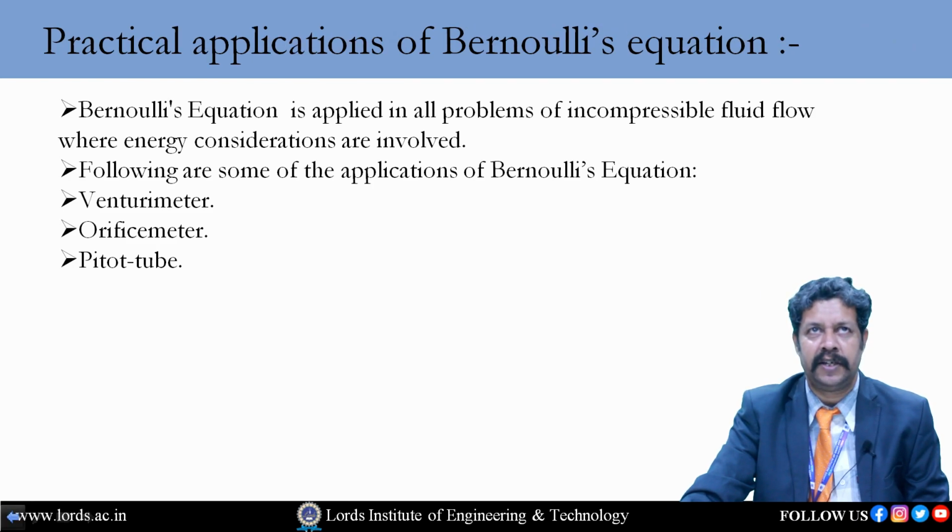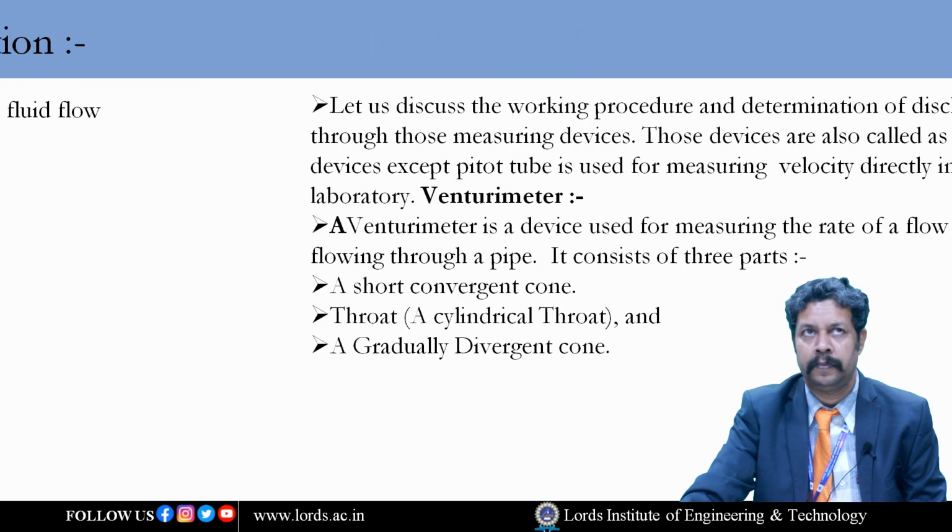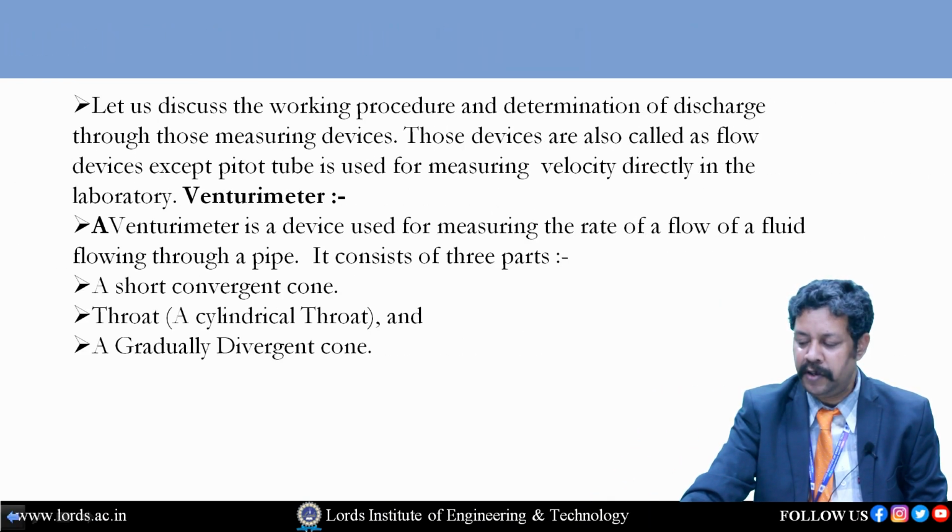So Bernoulli's equation is applied in all problems related to incompressible fluid flow where we are considering energy. And these are the following applications of Bernoulli's equation. Number 1, Venturi meter, number 2, orifice meter, and number 3, pitot tube. Out of these, Venturi meter and orifice meter are used to measure discharge only. Pitot tube is the only instrument in fluid mechanics with which we can measure velocity directly in the laboratory.